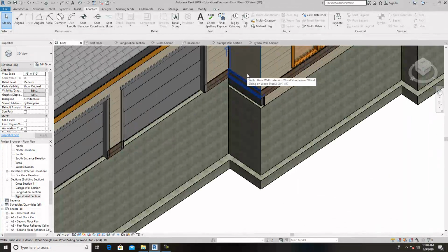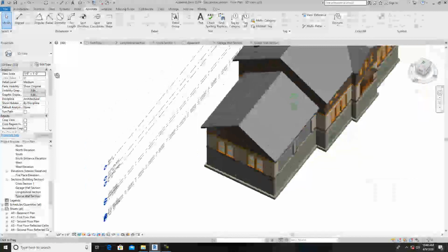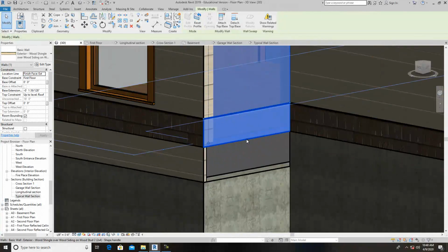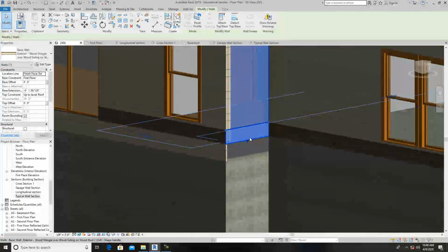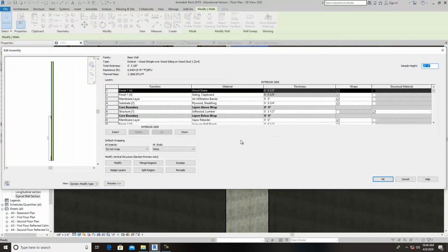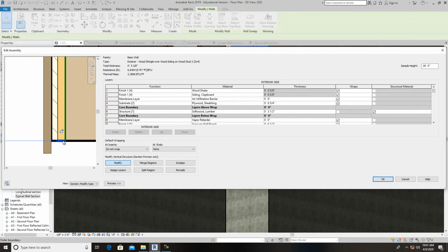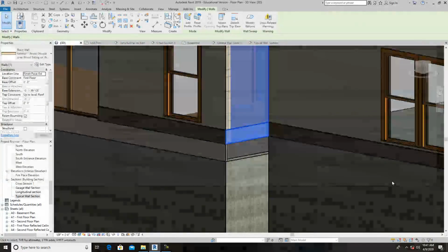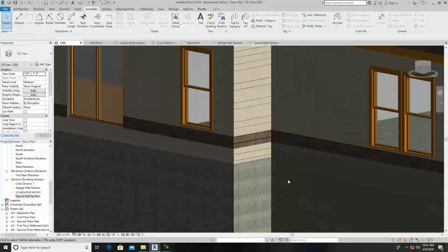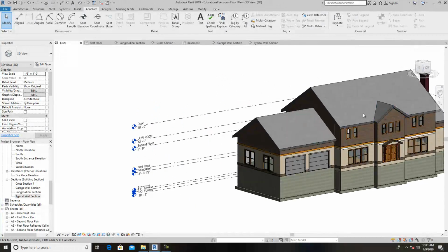Now over here it's not letting me do that because this is yeah, it is. It's going to let me do it. I was going to say it's a different wall, but so we need to go in there and just do an edit on that wall, and modify, zoom in here and make sure that that's unlocked. Yeah, it's unlocked. So I should be able to do that too on this one. Should be able to grab that and pull that down to there. Perfect. Good shape. So now that looks pretty good all the way around through there.